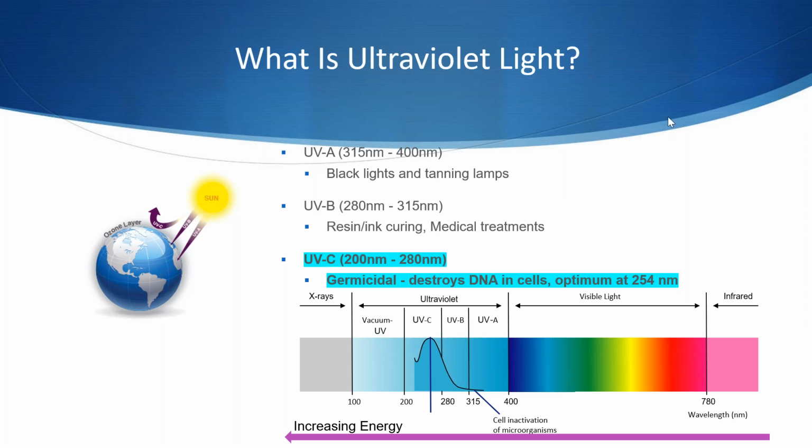The highest level of effectivity is at just over 260 nanometers, but it's optimized, meaning best harnessed and provided at the right cost and safeties and all of those things. So optimized at the 254 nanometer wavelength, which is right near that peak of germicidal efficacy. This is the type of lamp that most UV suppliers use, the UVC at the 254 nanometer wavelength.